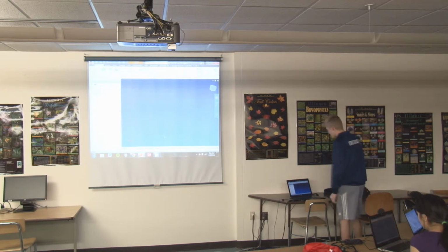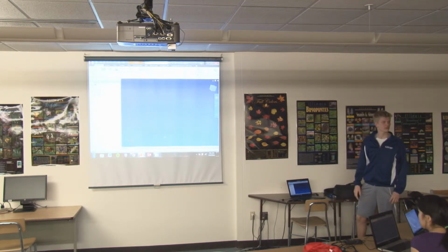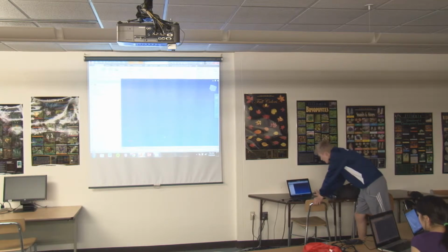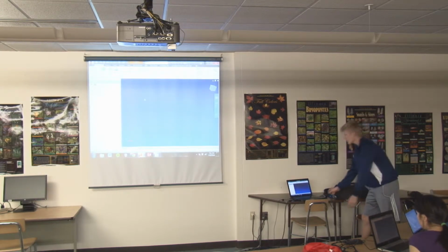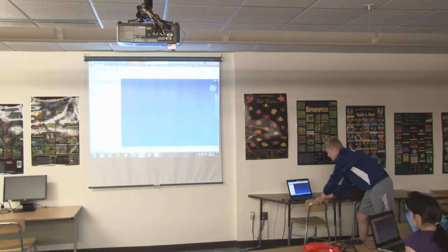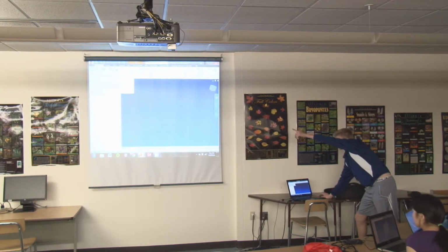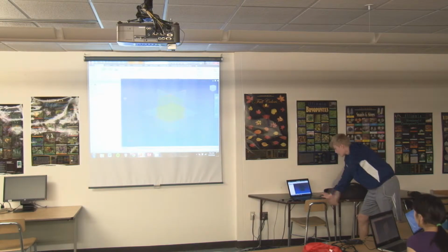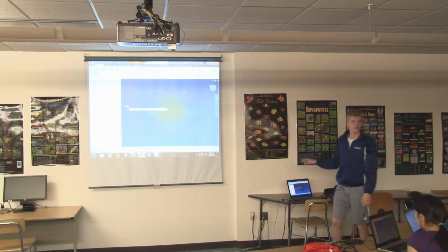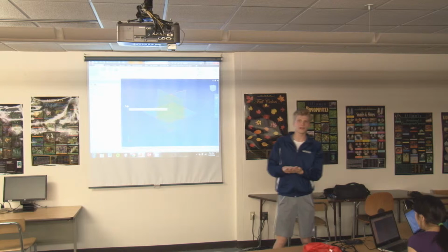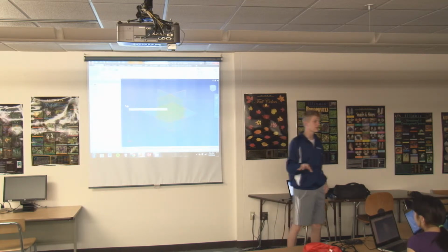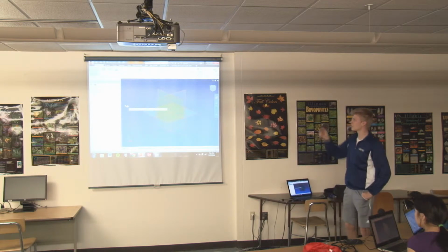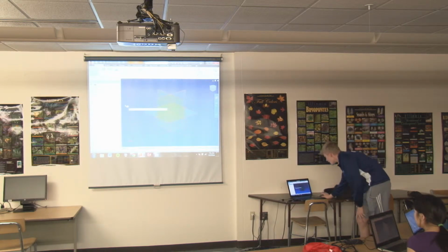So in Autodesk, which is Autodesk Inventor, that's what we're going to be learning tonight. To start creating a sketch whenever you enter the program, you go to the Create 2D Sketch button at the top of the 3D model program there, and then you just click it. What it'll do here is it'll bring up the three planes on your origin, your X plane, your Y plane, and your Z plane. The first sketch for the part that you make goes on whichever plane you select from there. It's really arbitrary which plane you select.